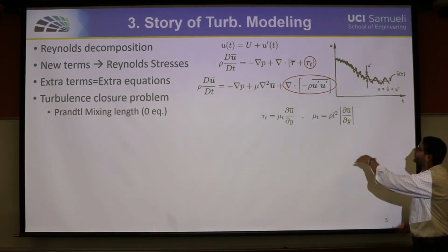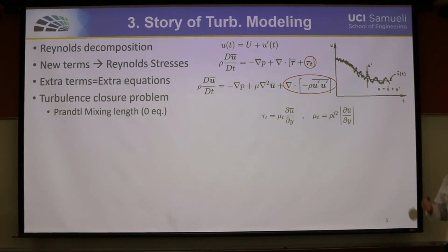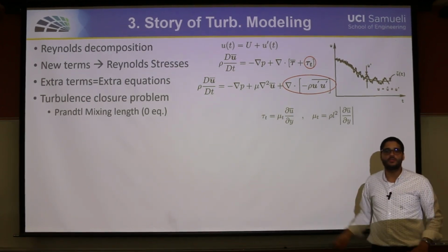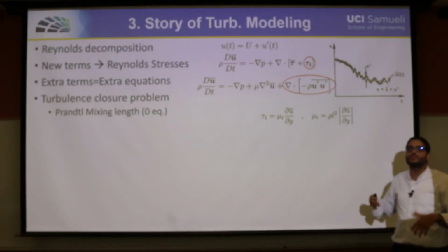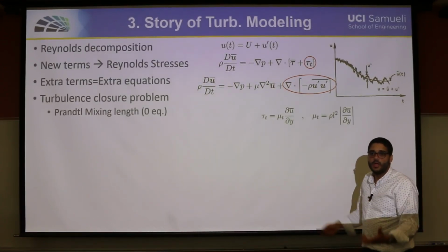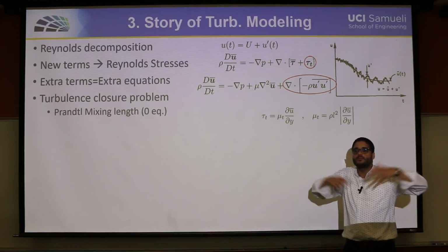But as you can see, there is no equation being solved here while you are doing this CFD simulation. That's why it's called the zero equation model. There is no dynamics. It's an algebraic model: give me that number, I'll give you that number. There is no dynamics, okay?